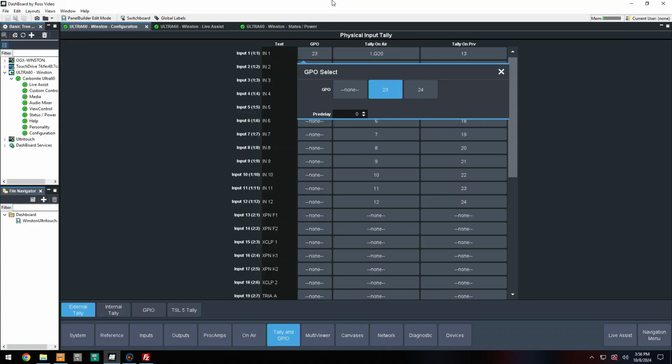But maybe, like we saw with 24, it's a device that can't support a level and it needs a trigger. So it needs a pulse. And a lot of times that's because it sees the rising edge and it waits for the falling edge to confirm that it's supposed to trigger. And sometimes you need to set those durations between 7 and 10 frames depending on the device so that they don't perceive it as noise on the line. It's held long enough that it triggers their interrupt.